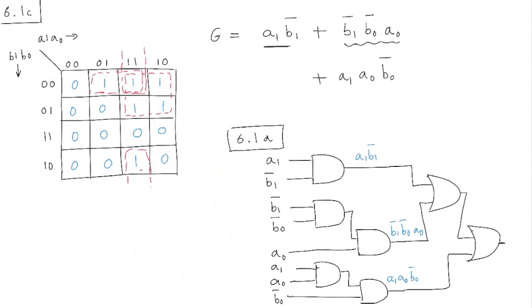Now in this question, you've been specifically asked to use 2 input gates, and that's why you need these many gates. But if you are not specifically told that, you can just use 3 input gates, right? So for example, if you wanted to generate this expression here, if you didn't have to use 2 input gates, you can just have an AND gate with 3 inputs going in and 1 output. And similarly for an OR gate as well, you can do that. All right, so that is problem 1. Hopefully that is all right.